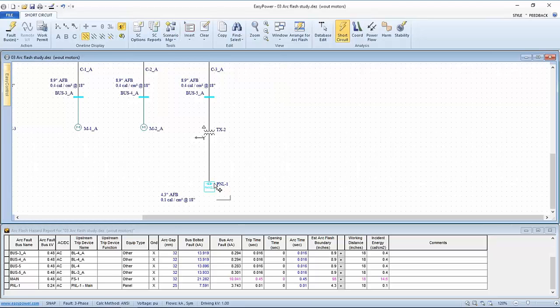So if I can erect a barrier, or if I can move that protective device outside the panel, preferably far enough away from the operator so he can work on this panel without fear of an explosion at the fuse, then I think life is going to be much better.